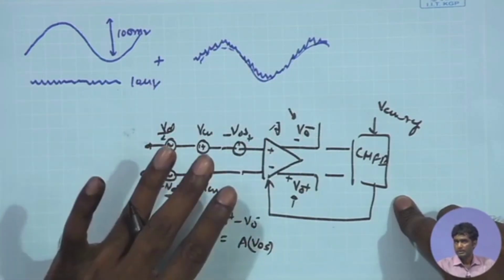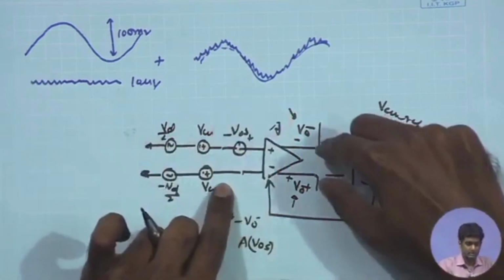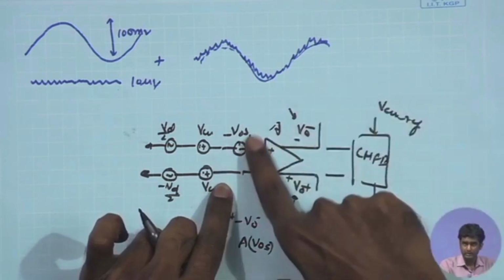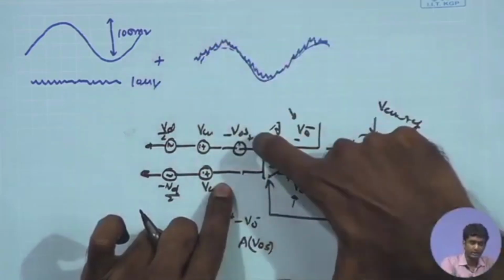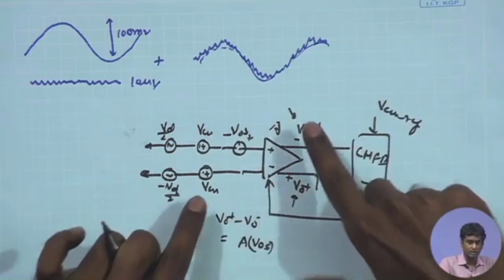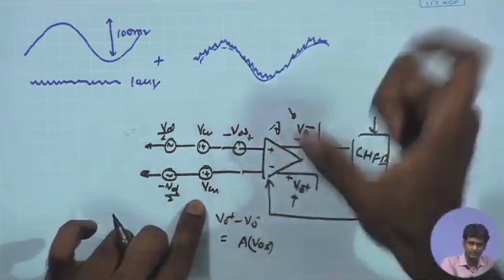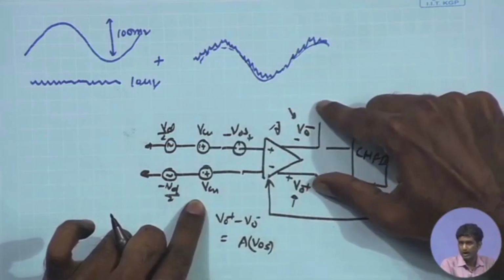So in case we go for the normal operation, suppose that you have a resistive feedback and then we are forcing the output common mode to have some value. A mismatch over here can occur if you have a different, independent bias for the input with respect to the output. Under that condition, any mismatch in the input side or the mismatch in the devices in the differential amplifier side can create a significant mismatch in the output levels.